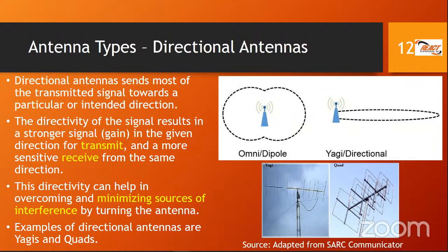But there are two concepts here. One, an antenna is going to be resonant on a particular frequency. Left or right or above or below that frequency, it's going to be less resonant. But there's also the concept of the bandwidth of an antenna, where an antenna could be resonant over a wider range of frequencies. But for some of the frequencies that amateurs are using, the bandwidth is so wide that you will hardly find an antenna that is going to be exactly resonant across the whole range. That is not typically what you will get.